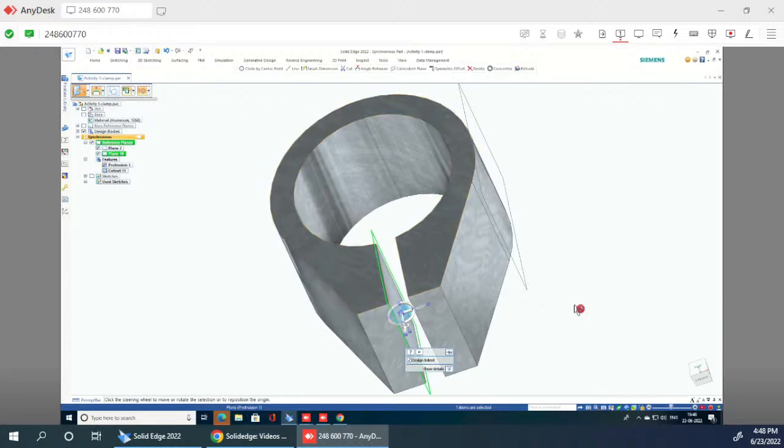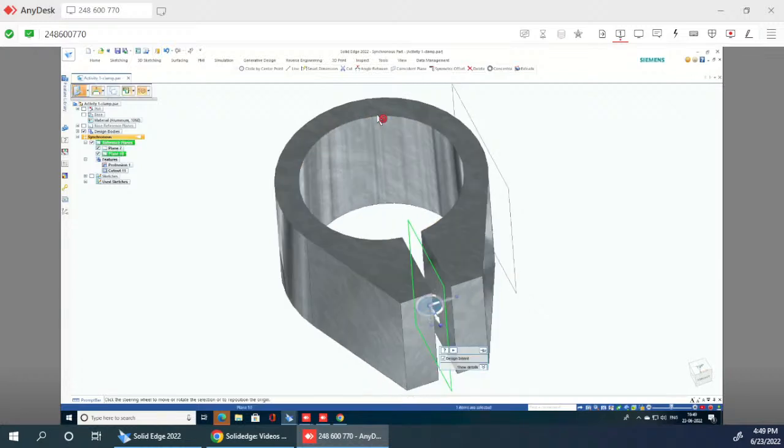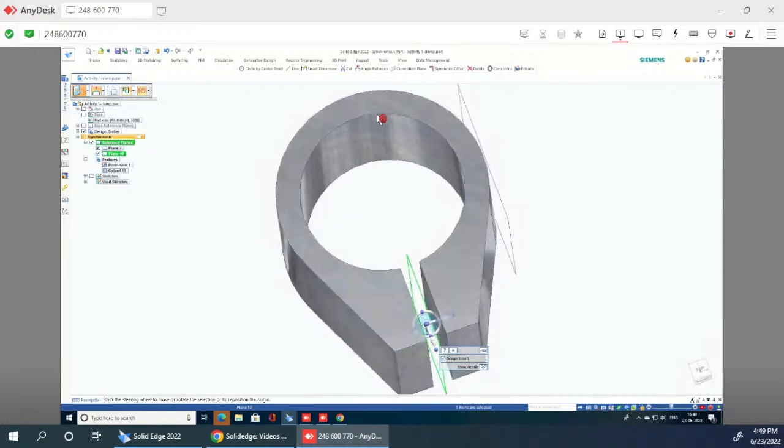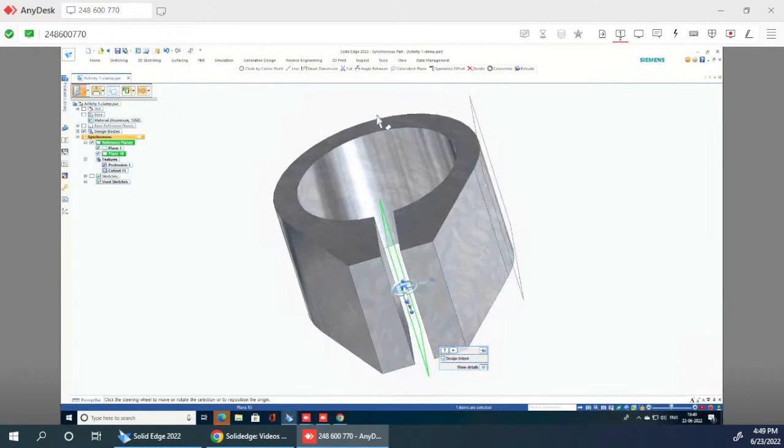Okay, so you have selected that now. Then click on this arrow. Okay, click on that arrow. And now click on the circle here. It should highlight. Wait for it till it highlights. Now it's highlighted. Now click on it. Okay. Now go to the top view and check where the plane is. It is in the middle. Now from that point again click on that arrow, give whatever displacement you want.